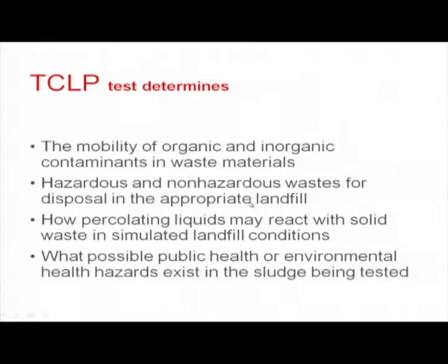Usually, it determines the mobility of organic and inorganic contaminants in waste material. The TCLP test will tell you whether a particular organic or inorganic waste is mobile or not, and classify hazardous and non-hazardous waste for disposal in the appropriate landfill. Before disposal of any hazardous waste, whether the waste is fit for landfill or not is determined based on the TCLP test value, because after disposal there should not be any leachate, and because of the mobility, it should not be leached out.